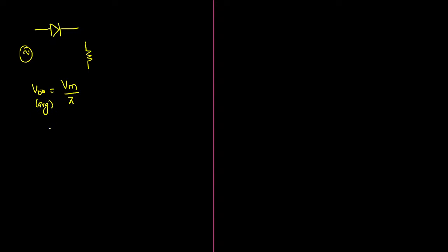Okay, sir. Then what can be the RMS voltage for R load? V naught RMS also will become simply Vm by 2 only. There will be no doubt. It will not be root 2. Remember one more thing. Okay, and it is very important to know how to calculate the input power factor. If you know, peak inverse voltage will be equal to Vmax.